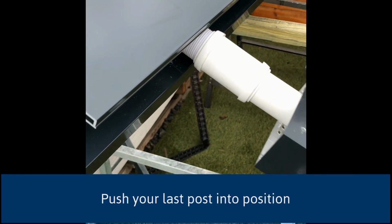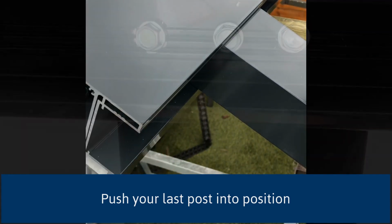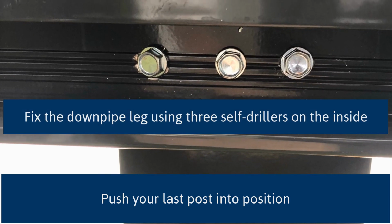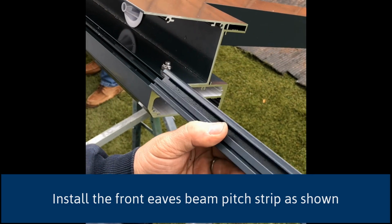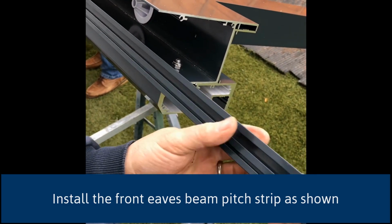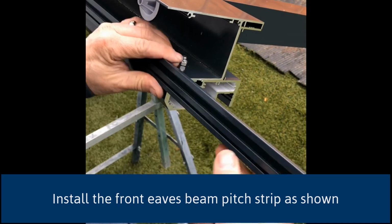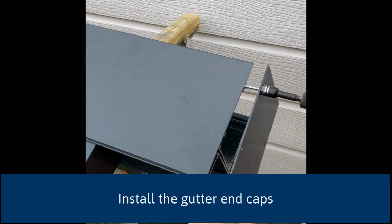Now push your last post into position. Fix the downpipe leg using 3 self-drillers on the inside. Now install the front eaves beam pitch strip as shown. And then install the gutter end caps.